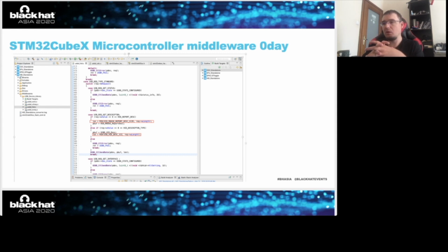We have a code, so nothing stops us from, for example, selecting one of the I/O ports on the target board, using it to set a trigger just a little bit after or before the one or the second function, and trying to send a glitch that will finally corrupt this function, and maybe the size we craft in our USB message will overwrite whatever was before.